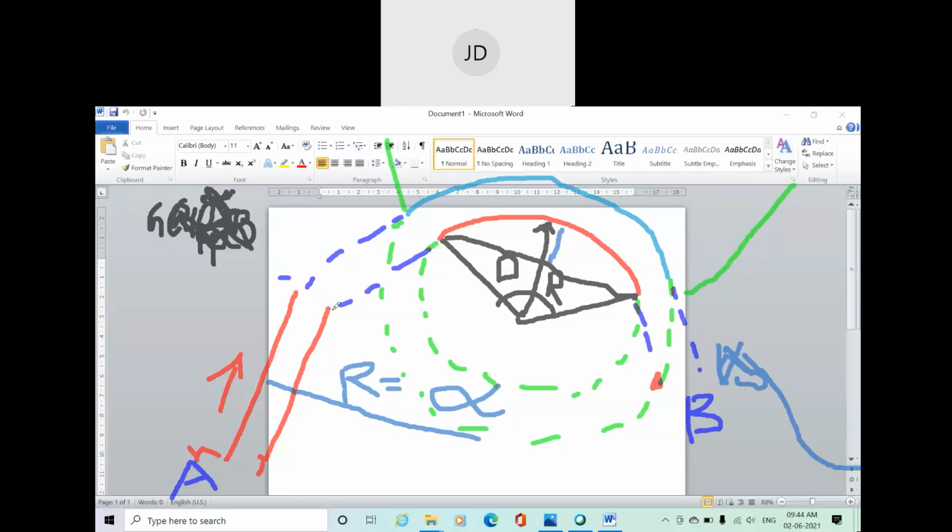The gradient, we already discussed, is the longitudinal slope. It is not directly provided in the circle. It is gradually provided from straight to circle. And this gradual application of gradient and super elevation is provided by introducing a transition curve between the straight curve and the circular curve, even between compound curves.